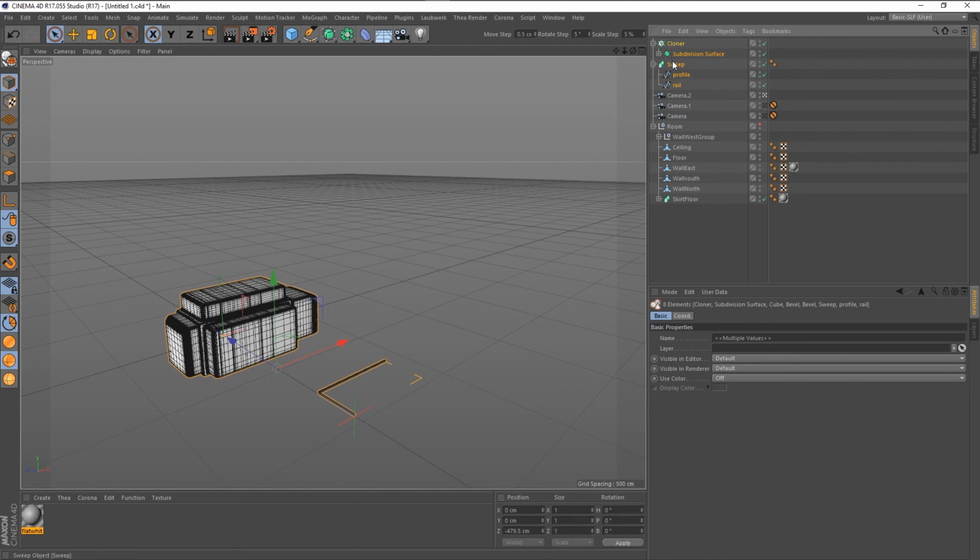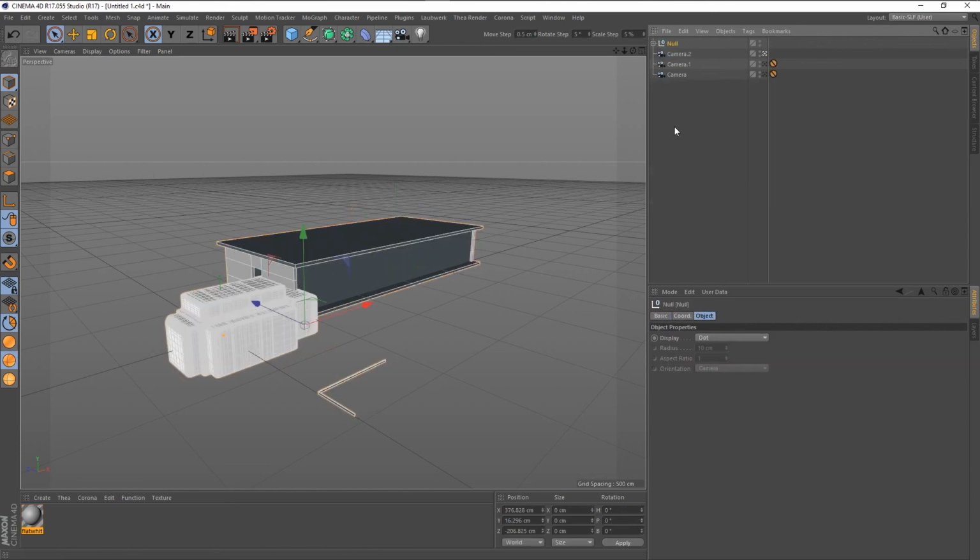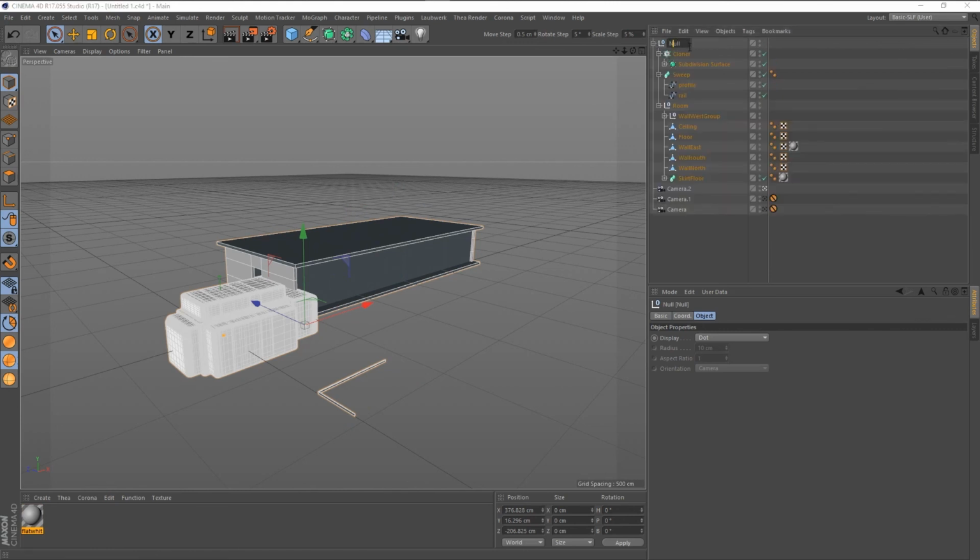Click on it to select it, and it looks like I have the room turned off. We could even group the room. So middle click with Shift and Control to select everything there, and then I can press Alt G. Then I'll put them all inside of a group, and I can call that whatever. So here's my new group. And that's how groups work.